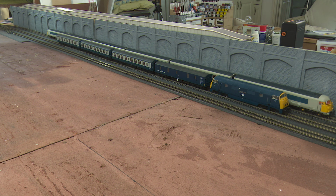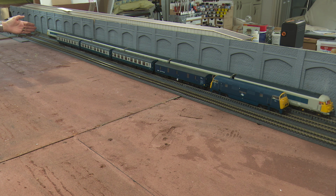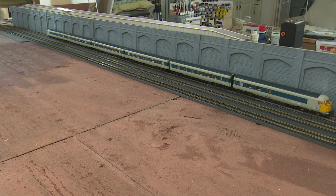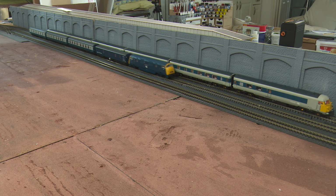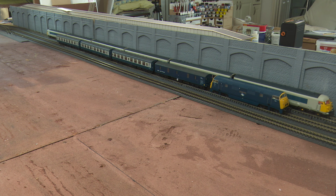So what I shall do is just adjust the ramp speed, which is 10 inches, so that it doesn't move 10 inches down here before it starts to slow down. It will slow down immediately and make more of a gradual slowdown. So let's see what she looks like now with that adjustment. Much more realistic, just the job.